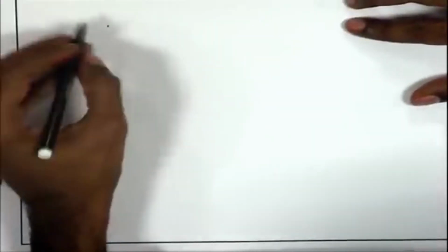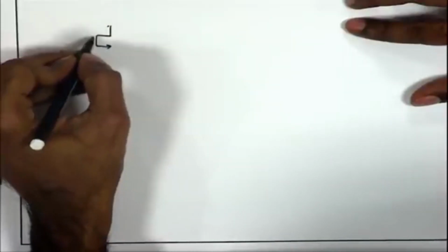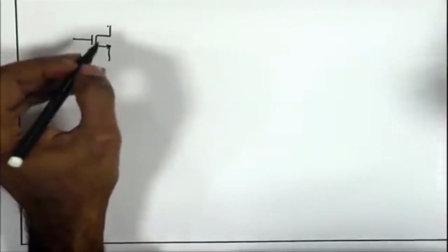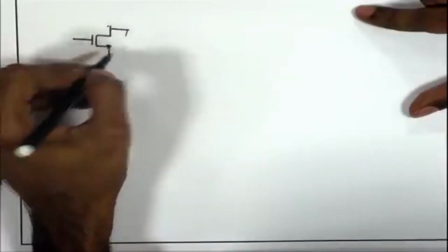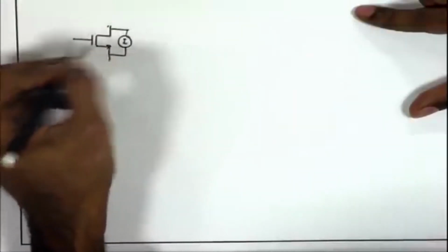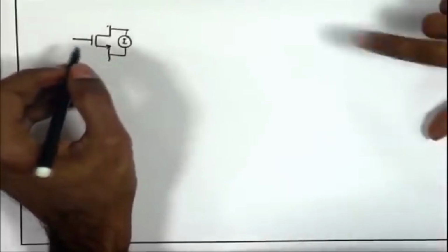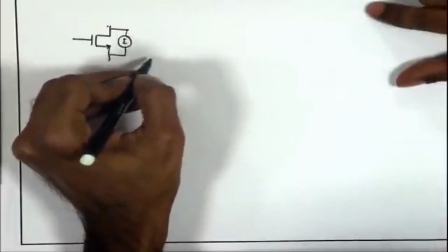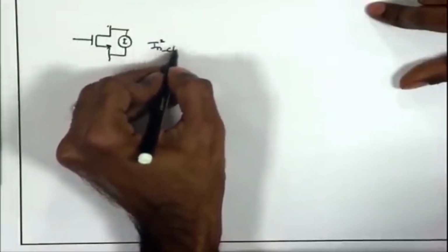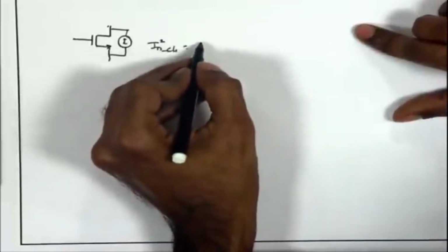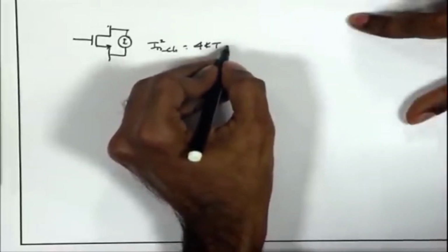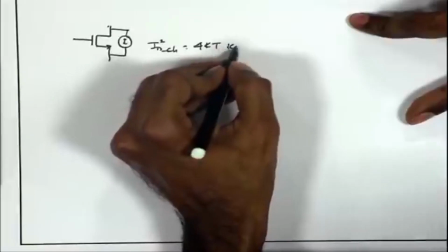So, just like a resistor, when the MOSFET is on, it is in saturation region, it is having a current flowing through the drain to source, and if I talk about the small signal current, that is proportional to the Gm. So, effectively the transistor is having some effective on resistance in the channel proportional to Gm. So, we can say the effective noise current source I n square channel is going to be defined in a similar way, 4 kT some proportionality constant, say k naught times Gm.